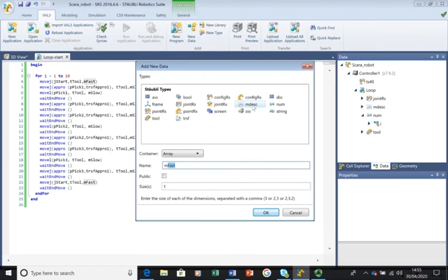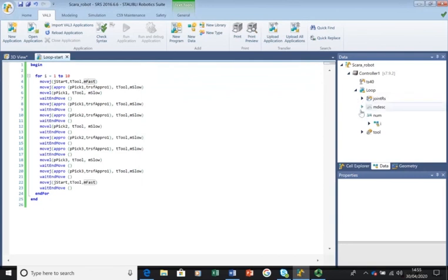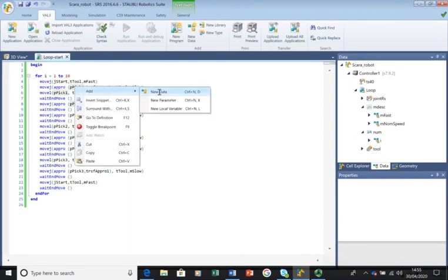And we can put the values of what that is, so we don't have to write all this big code, this big value in every time. We just save it as a variable, and if we need to change it, we can just come to the motion descriptors, and it will update the whole program. So if we go to motion descriptor now, we've got this mfast in there. We've got a variable called tppick, right click, add, new data.